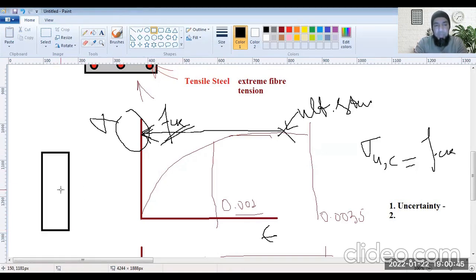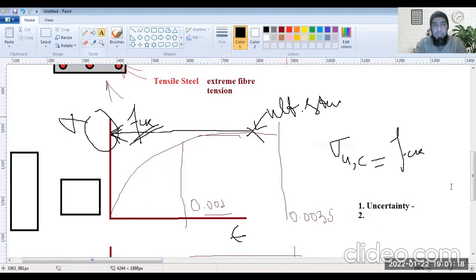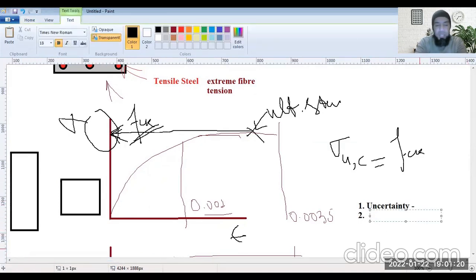That's why the cylinder comes to have lesser strength, because it slightly buckles as well at the same time. The aspect ratio has got an effect on that. The aspect ratio between this height with respect to this width, जो कि cube में नहीं है. Cube has got aspect ratio of 1. Cylinder में it has got an aspect ratio of around 2. तो उसमें you have lesser strength there. So cylinder में shape factor plays a role.